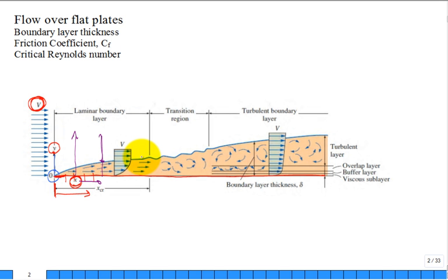What's happening beneath that line right here is that the fluid velocity is not cap V anymore. It's lower, and it goes to zero at the plate surface because of the presence of the plate and viscosity. So you get this velocity profile. They've only shown you one of the velocity profiles, let's say at this location x, but they could have shown you one in here and one in here and one in here. They could show you a bunch of locations x.